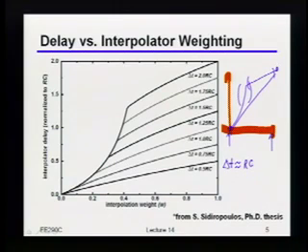Okay, so again, the key important point is to make sure that if you're building something like this, you have to be controlling the edges so that their slopes are directly tied to the difference in delay between the two things you're trying to interpolate between in the first place. Okay? So now, how do you think you're going to do that? How are you going to make sure that, in all of the different processes and all the different corners and all the different voltages, all the different data rates you might want to run, your phase interpolator actually has the right edge rate?